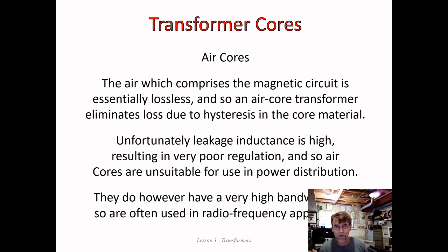Before I move on with the but, I see the word hysteresis there. That's what I'm talking about, the flip-flopping back and forth. It's called a hysteresis effect, and it causes a delay in the rearranging of the atoms to magnetize the core, because the field is constantly changing and constantly changing direction. With an air core, none of that's happening.